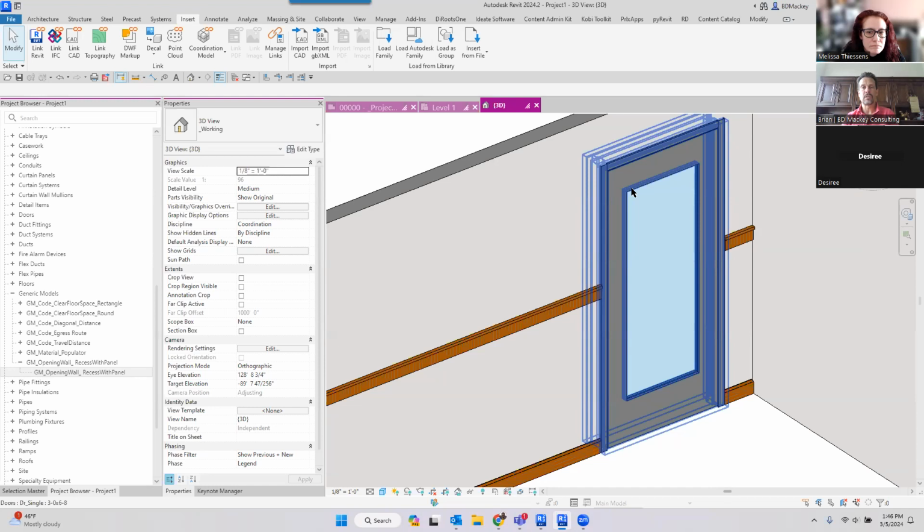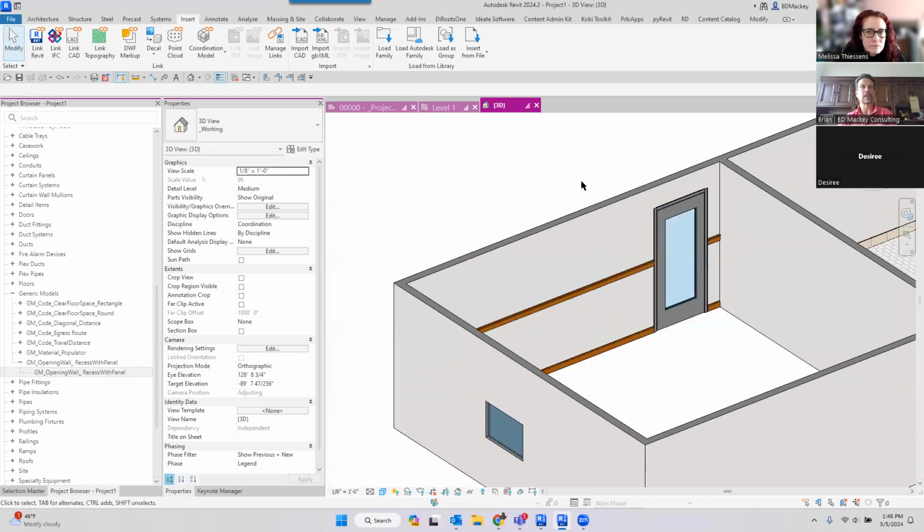A lookup table doesn't even work for that, because you're pulling data from the nested family and pushing it into the project or into the other family. So that doesn't work. It is a manual process. If you change the 12 by 12s and that's got to fix something else, you would have to do that also. So it's one of those things where it kind of works, but definitely not probably the way you want it to work.